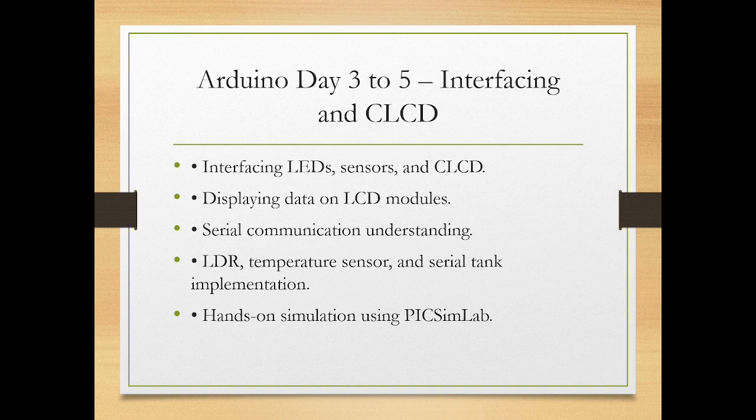Now, serial tank. The serial tank experiments use the serial monitor to display sensor readings like water level or an analog sensor. Data is sent from the microcontroller to the computer using UART communication. The serial communication syntax is Serial.begin(9600); that starts the serial communication, and Serial.print sends data to the serial monitor. We will see that in the project implementation.